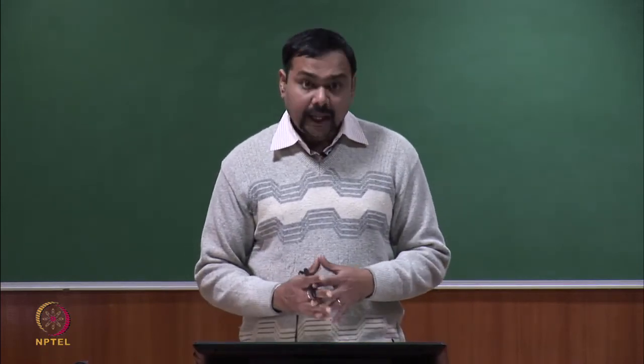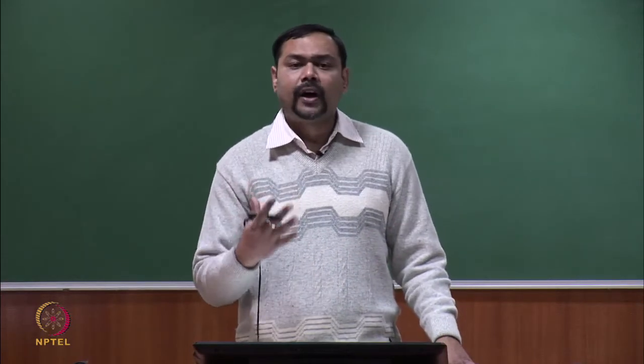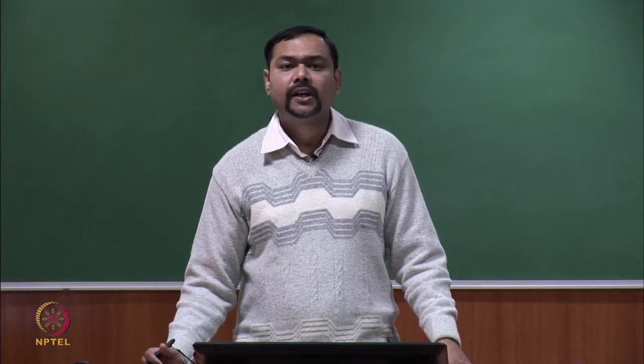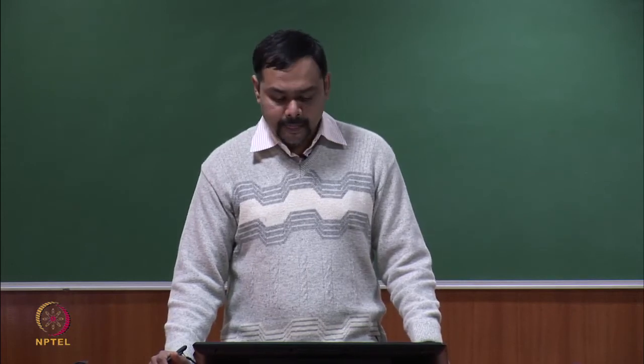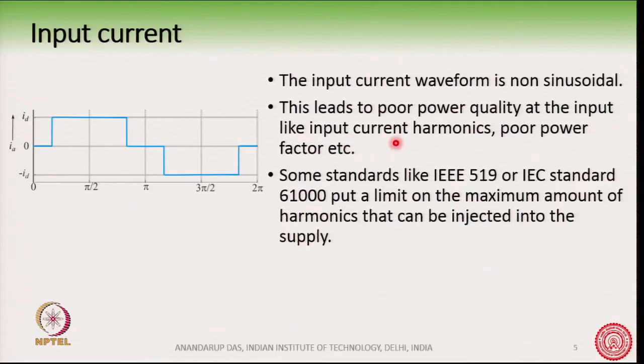So, in that case, the degree of pollution that we are injecting into the supply can be quite high, can be substantial, and this will lead to a lot of input current harmonics and consequently poor power factor. This will lead to an overall deterioration of the input supply voltage quality, which can be supplied to other loads. So, it can cause flicker, it can cause unwanted disturbances to other loads, etc.